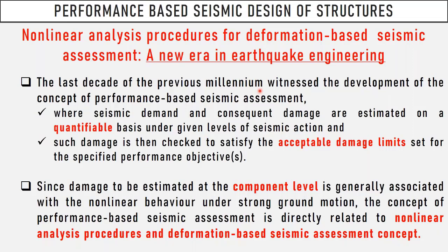This time, we had another tool to assess. We have the seismic demand, and consequent damage is estimated with quantifiable parameters. Now we check it with the acceptable damage limits and say, okay, it is acceptable or not. But this time, again, we are quantifying the damage in different aspects. Like even we go to strains in some cases, concrete strain or steel strain, in other words, deformations.